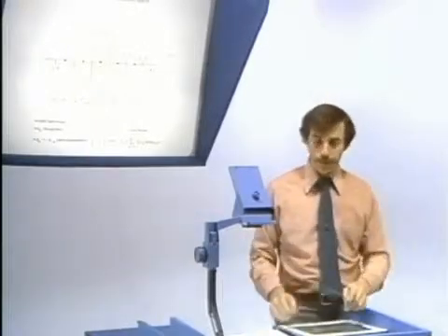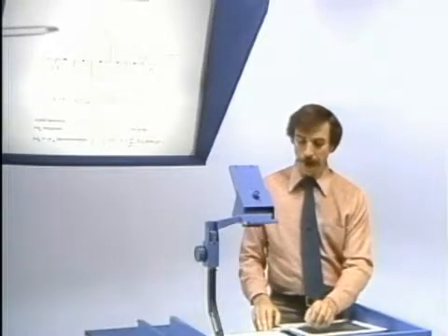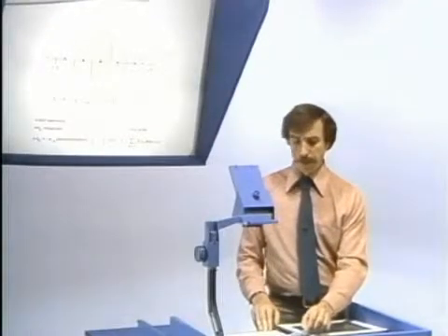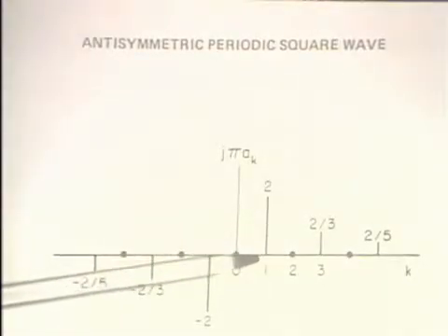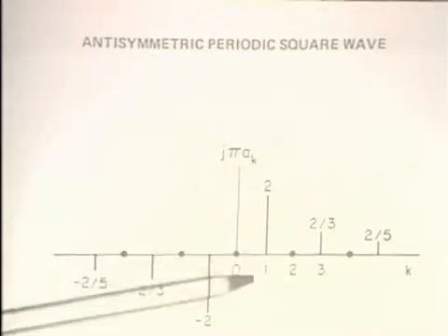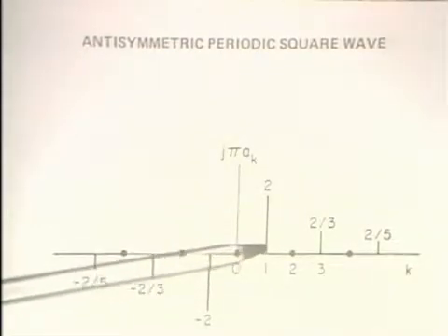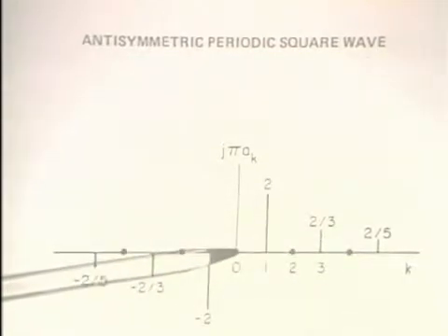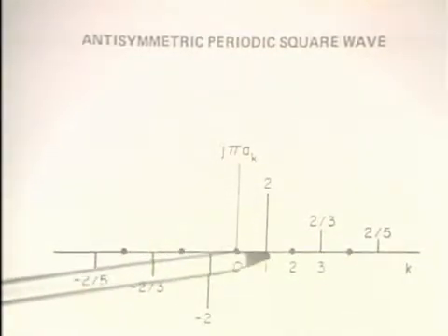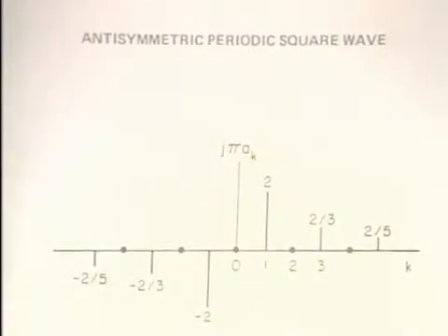As an additional aside, which I won't exploit or refer to any further here, but just draw your attention to, another aspect of this periodic square wave, the particular one that we chose, is that it is what's referred to as an odd harmonic function. In other words, for even values of k, the Fourier series coefficients are 0. They're only non-zero for odd values of k.